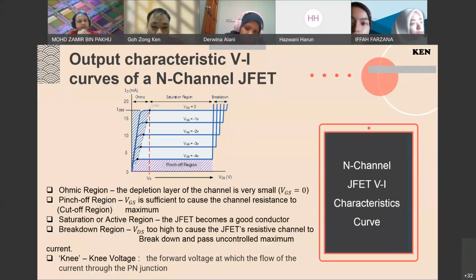I think the depletion layer will also break down. Yeah. Maximum current, due to too high current flowing through the channel. So that means the depletion width is not only controlled by the VGS. VGS also plays some role in the width because it affects the current anyway. Just like the limit of the JFET for blocking the current from flowing through the channel.